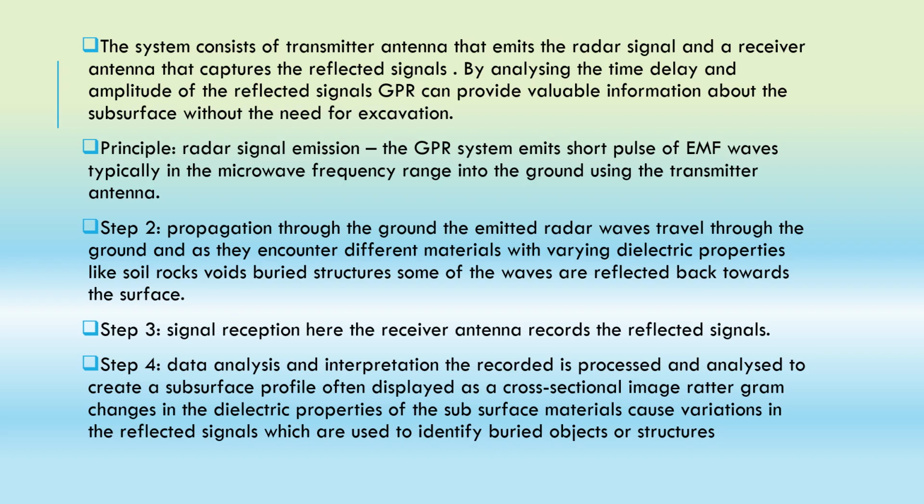Analyze and interpret the recorded data, turning unprocessed data into processed data, to create a subsurface profile, often displayed as a cross-sectional image, a radargram. Changes in dielectric properties of the subsurface material cause variation in the reflected signal, which is used to identify buried objects or structures.